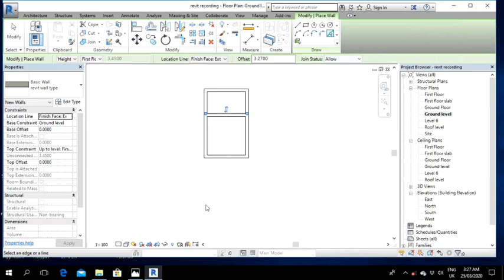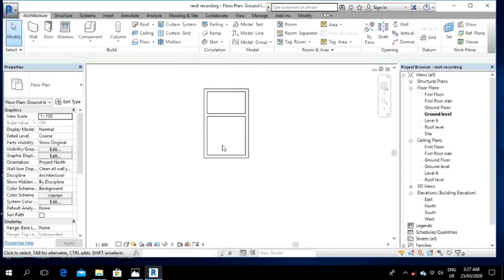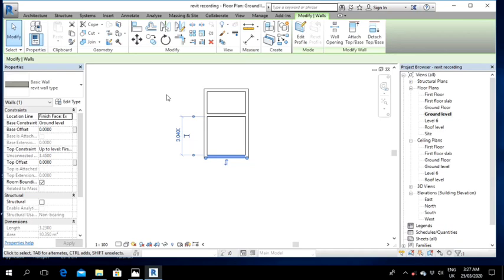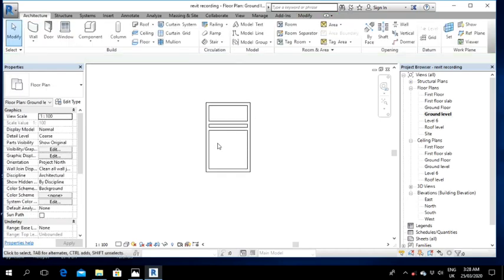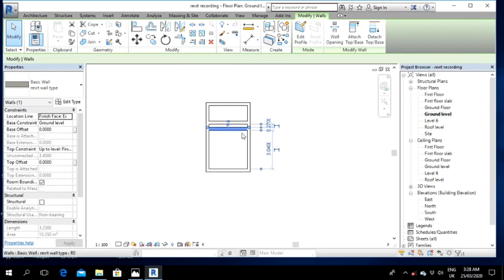So I'm going to draw the offset for that. Escape a couple of times, select this, right click and click on create similar, then tap this offset, type 3.77. Okay, when I hover a couple of times from there, it gets me there. Now I'm going to have to escape a couple of times and then give these walls their right dimension.